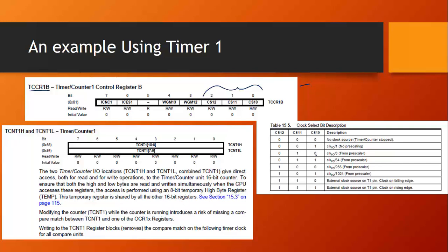that determines how fast your timer will run, because it derives the pulse for the timer from your main crystal, which is on the board. And I'll show you how that calculation works, but you can see there's multiple options you can use here to basically set up the clock for the timer, if you will.